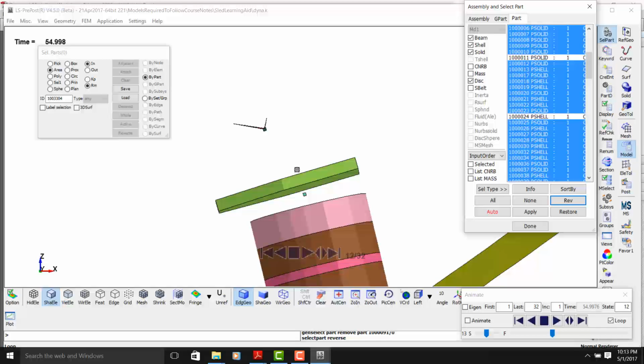That is the only value they can get for neck forces and neck moments, the loads, whatever the load cell gives. But because they are measuring it higher, they have to correct that so that they know what is here. This is the real point of interest, but they are measuring it 0.7 inches higher. And 0.7 inches turns out to be 17.78 millimeters.